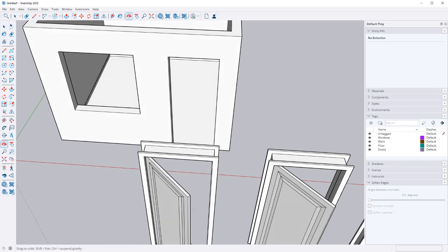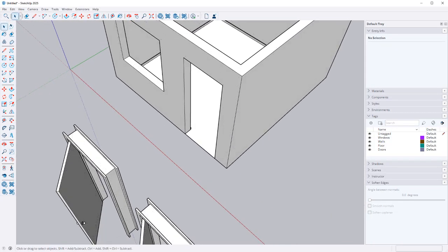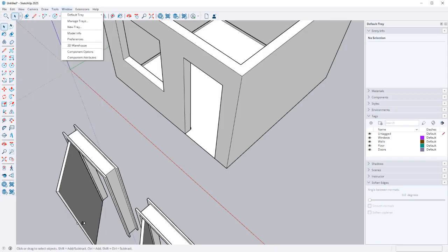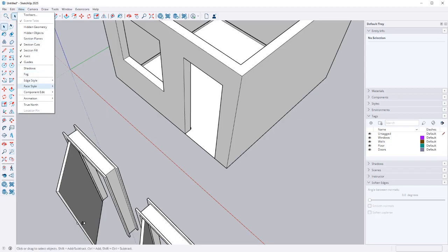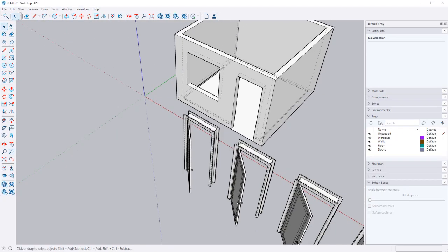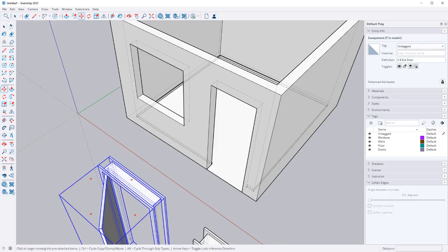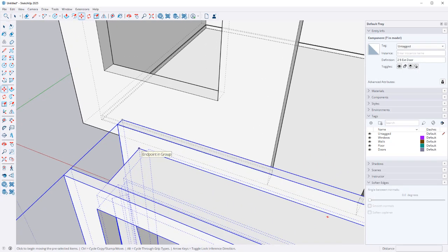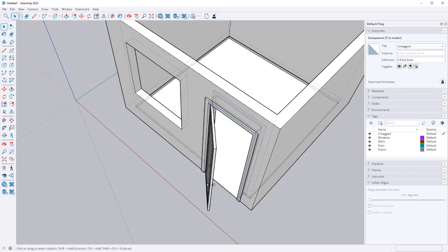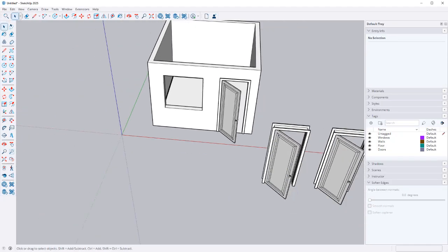To place this door, you have a button on your keyboard, K, and I forget where this one is because it moved around at some point. Back edges. Here we go. So K, under edge style. If I hit K, you can see that all of a sudden I get a bunch of these little dash lines everywhere as I toggle it on and off. So if I hit K, I can now reference this corner here. So again, where I want this to meet with the wall, I can grab this, put it in right there, and now I have a door as part of this space.